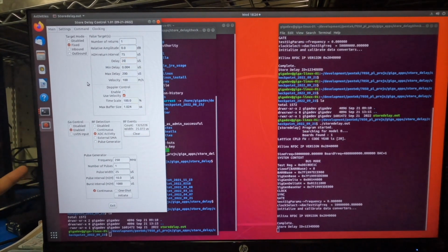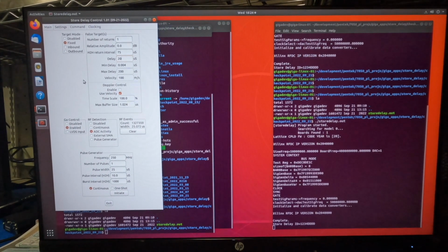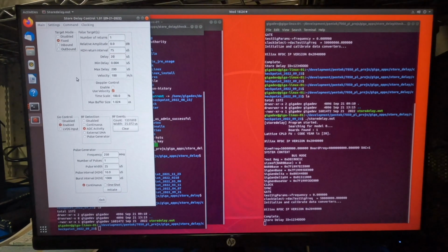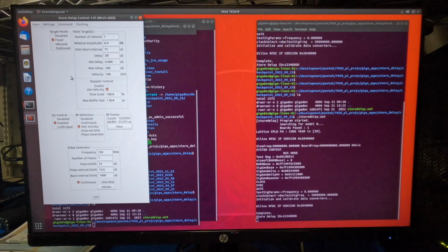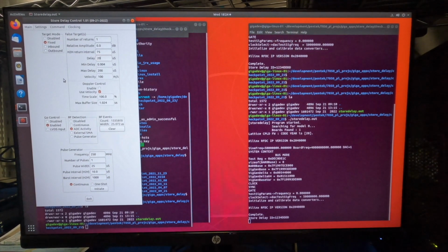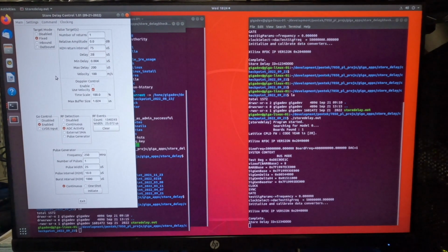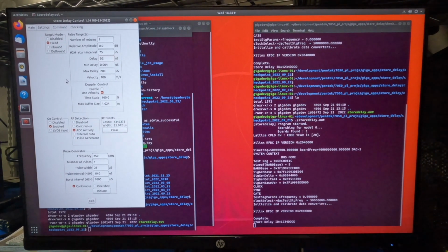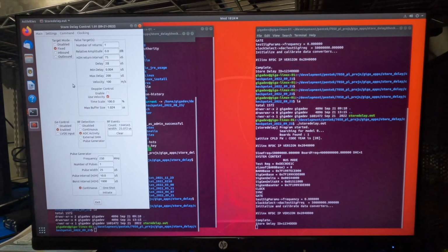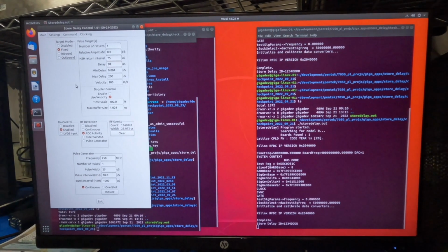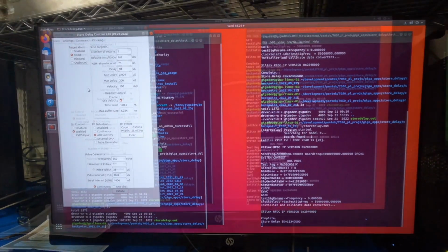Now the only mode we're going to show you in our series of videos today is a very simple multiple range false target application, and a subset of that is also the minimum delay cover pulse, which is also expanded into a possible application for a range pull-off jammer and also a Doppler pull-off jammer. So an RGPO or a VGPO we can do with the same setup.